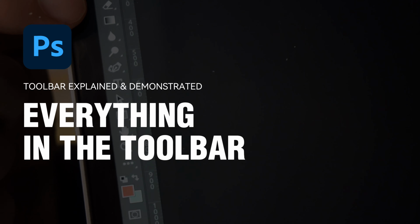1. Hold the Shift key to make your rectangular selection a perfect square. Also, holding the Shift key can give you a perfect circular selection when you use the elliptical marquee tool.